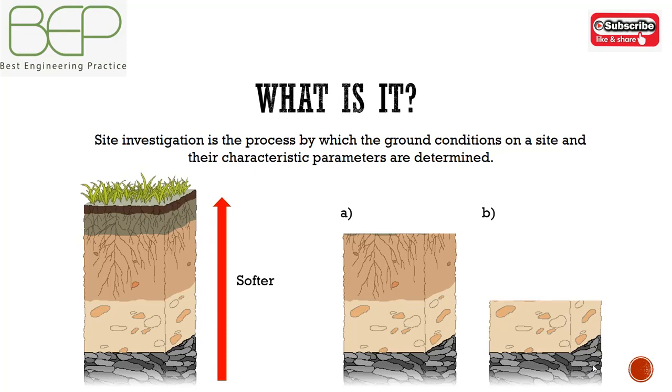When the construction method is not defined, it is difficult to argue that any design is either reasonable or possible. We can conclude that these two techniques will lead to completely different pressure distribution and magnitudes between the soil and the structure.